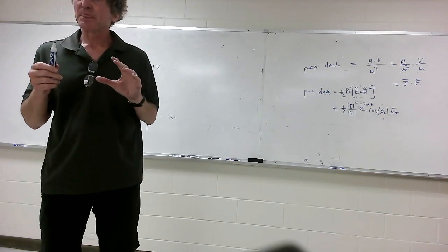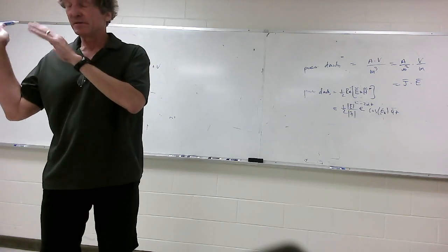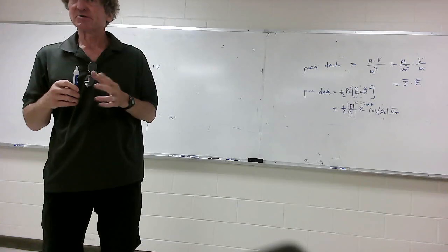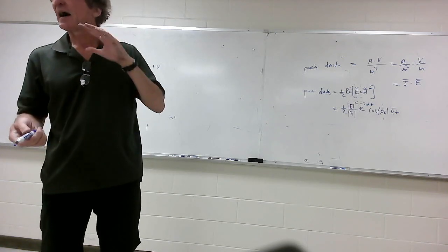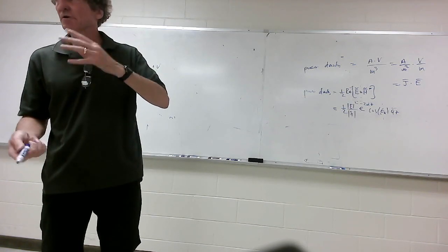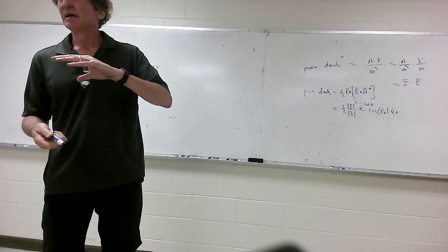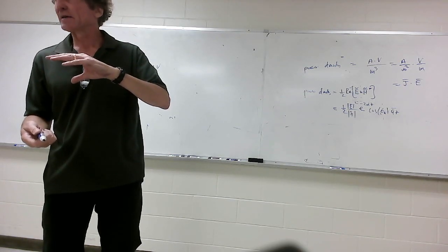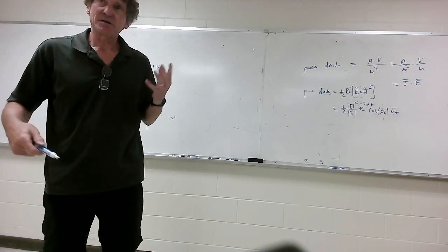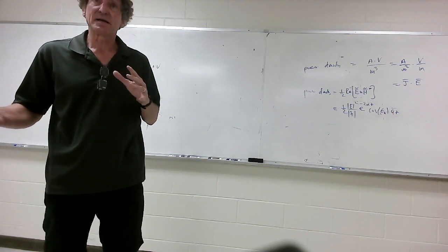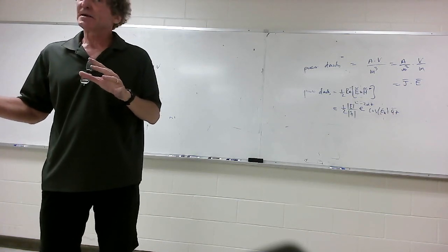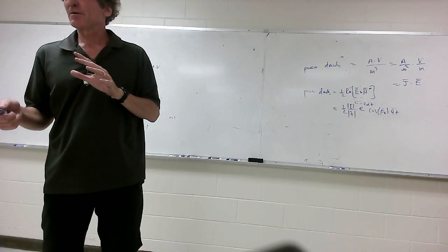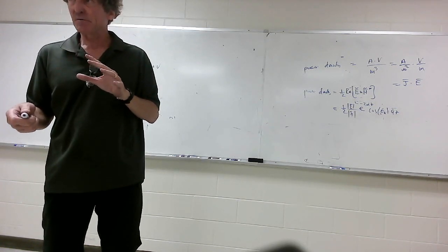I've been around a railgun, this is years ago, and when we were building it, they showed us some stuff. So they have these high energy density capacitors storing an enormous amount of energy, DC in it. And they showed me the aftermath of one where reverse current got into it. Basically, they're discharging huge currents, 20, 30 kiloamps, but it went through in the wrong direction and changed the polarity, and the whole thing blew up.